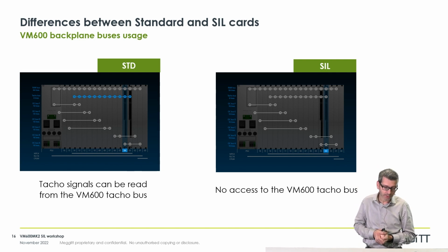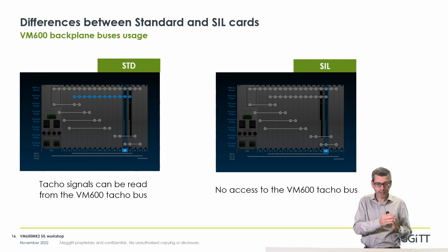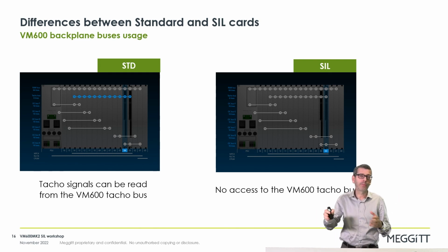And then it's important to mention that MPC4 SIL can only drive RLC16 SIL. You cannot mix MPC4 standard with relay card RLC16 SIL or vice versa.